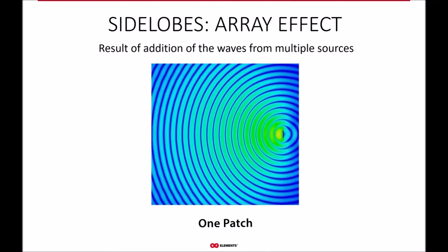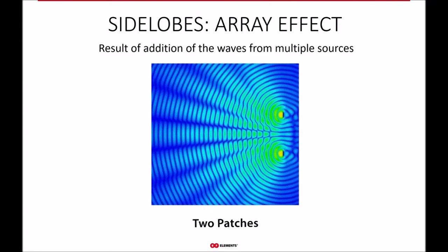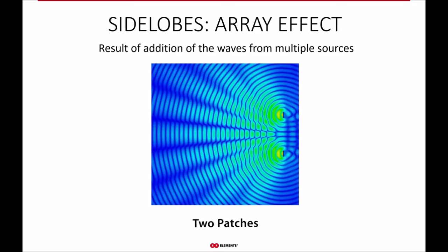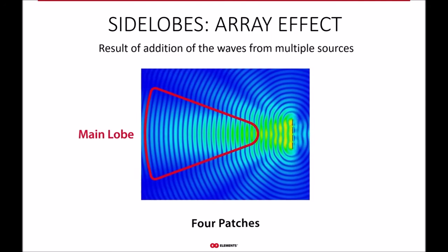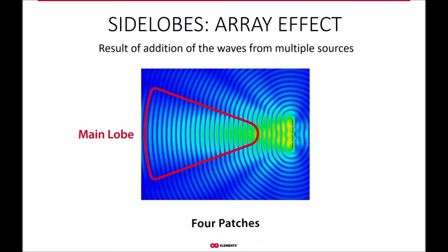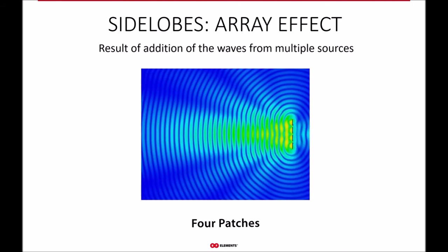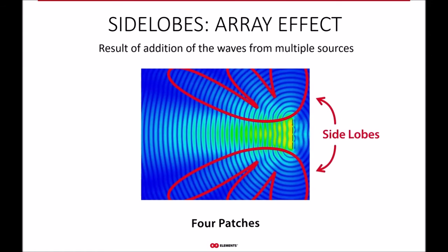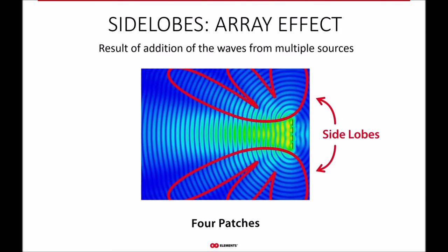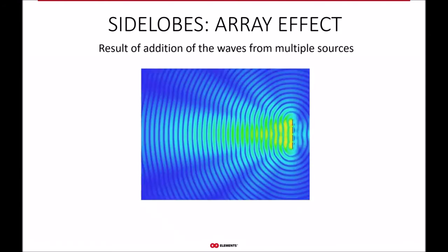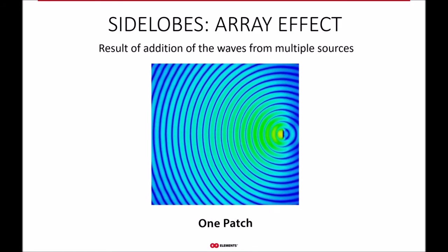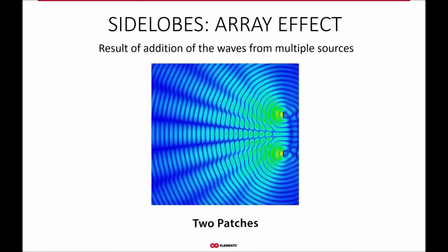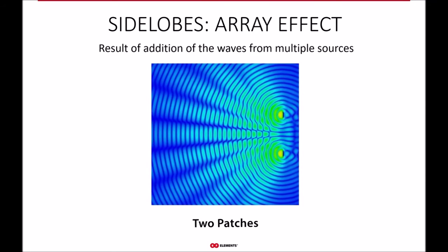So in the symmetry axis of the array is located the main beam, which is the strongest. That's what we're interested in. Any other lobes outside that main beam are side lobes, which in the RF engineering lingo are called grating lobes, if you will. And these are the side lobes a typical patch array has in the elevation plane. So when looking at the antenna from the side.